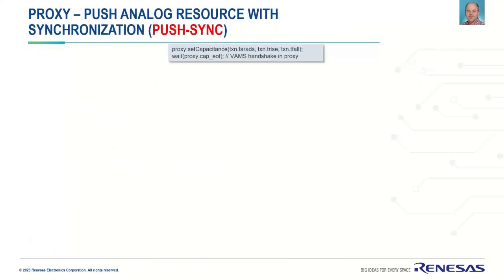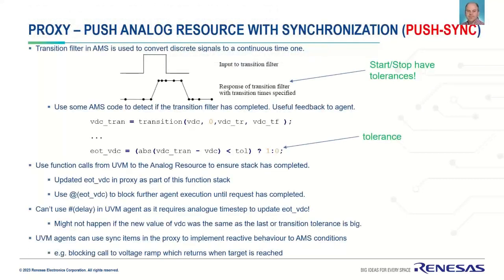So you're not doing that with a cross, because probably a cross would be an overkill way of doing it. Yes, and you can just do it more simply. If it's a voltage, the tolerance is going to be 1e to the -6. So there's going to be a time point there anyway, so you don't really need to. There'll be a time point at the transition. There should be, but you've got tolerances on it. Exactly, but what I mean is you don't want to force yet another time point just to get an accurate cross. Correct.